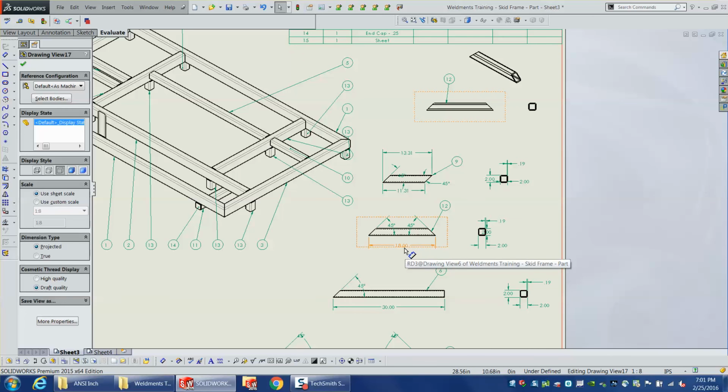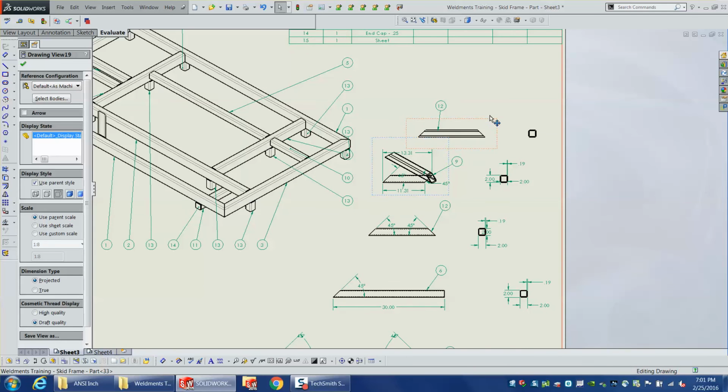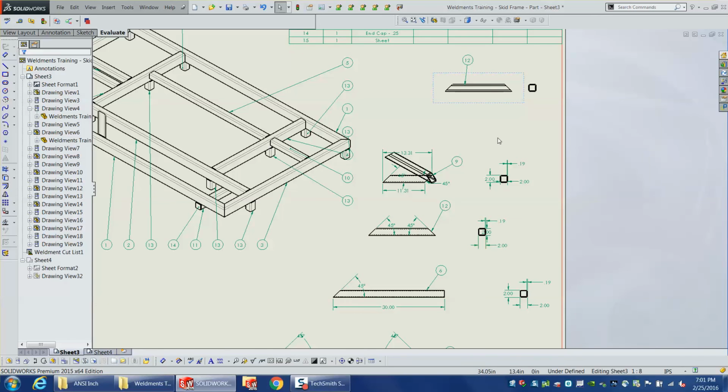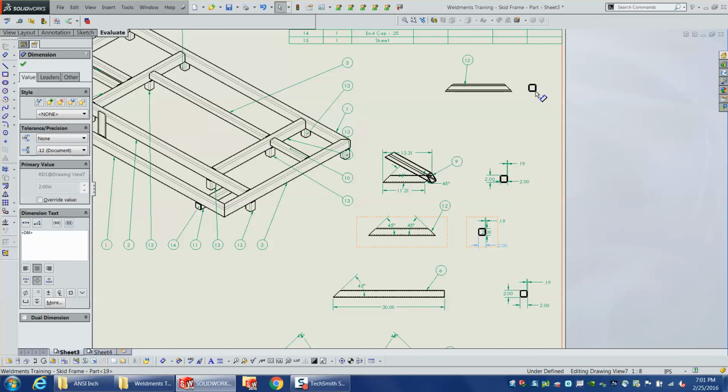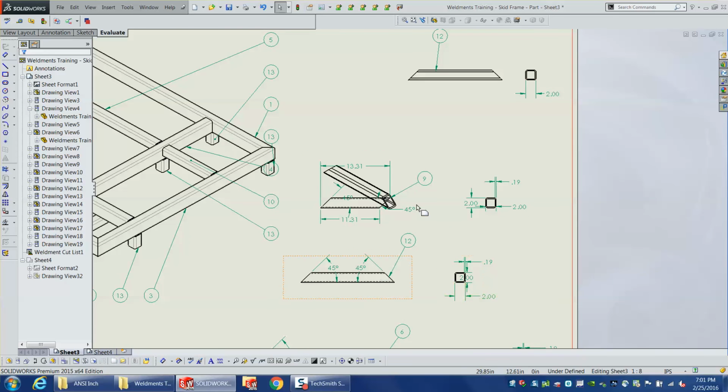If you hold down Control, deselect your view, then hold down Control, click on the dimension and drag it over to the new view. It actually copies it right to that view, to the same things that it was attached to in the other one. If you hold Shift, it just does a move. You can go view to view in the same part, the same way.